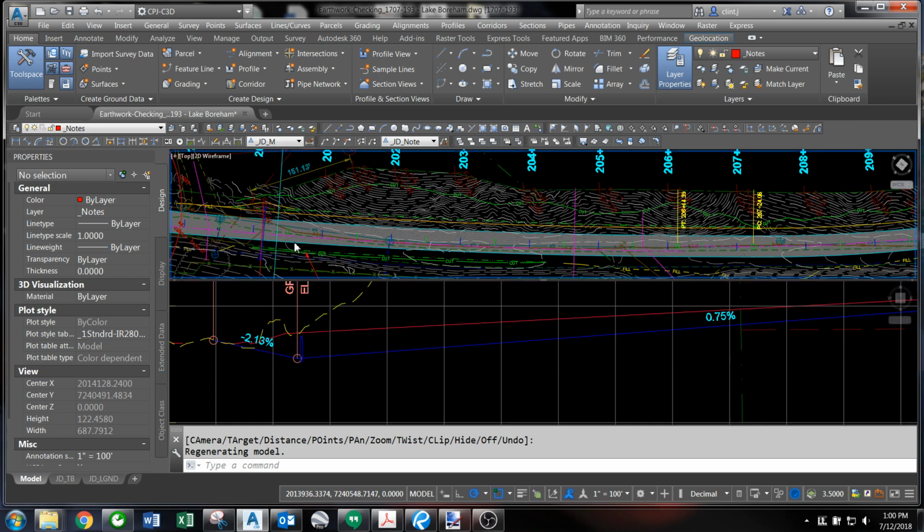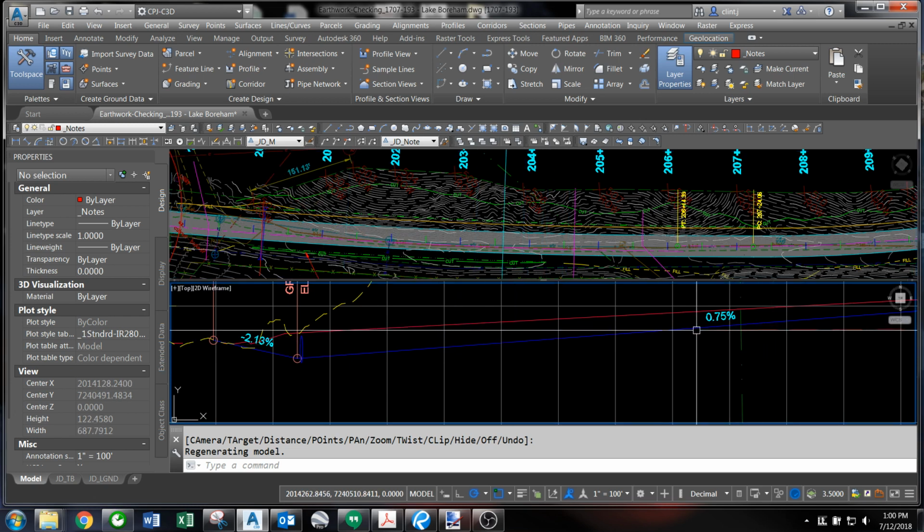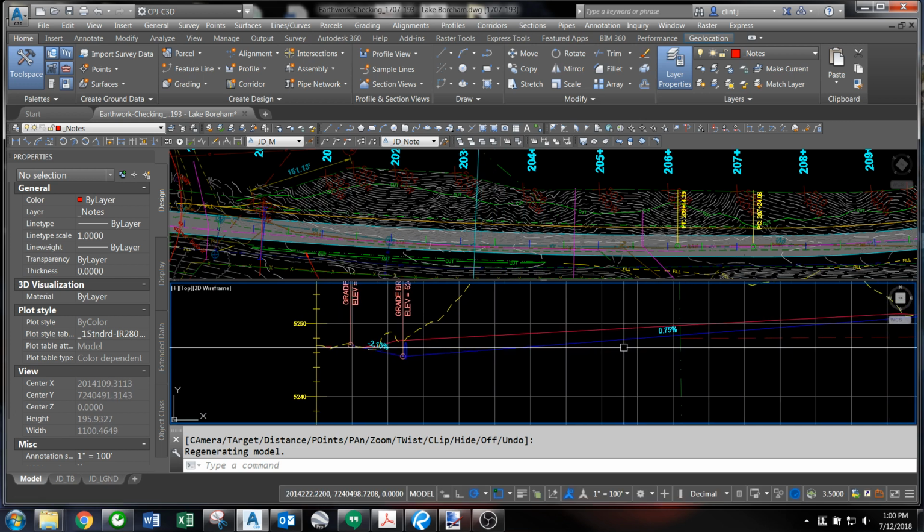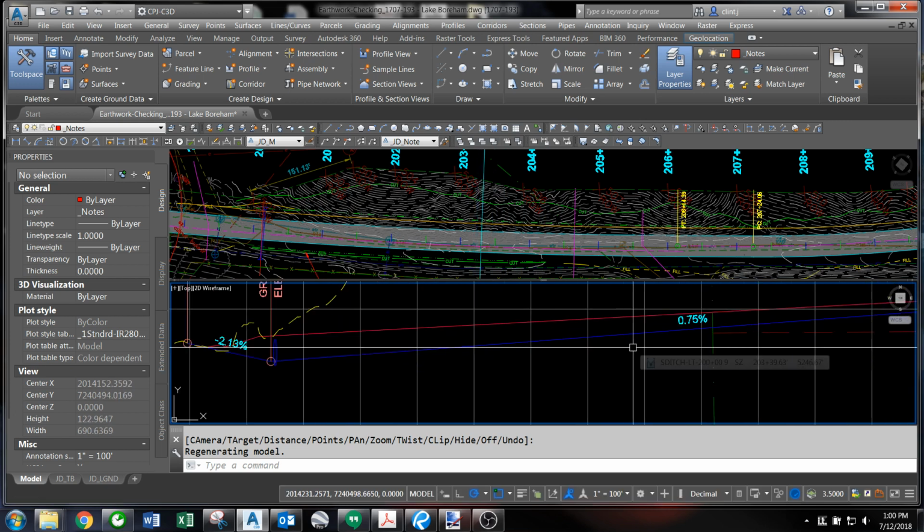Also here you can see, as I come along, that my orange line where my ditch would have been is no longer where the current ditch is. The ditch is now to the northwest, because as it got deeper, away from what the typical section would have shown, it also had to get further away from the road in order to maintain the same slope.